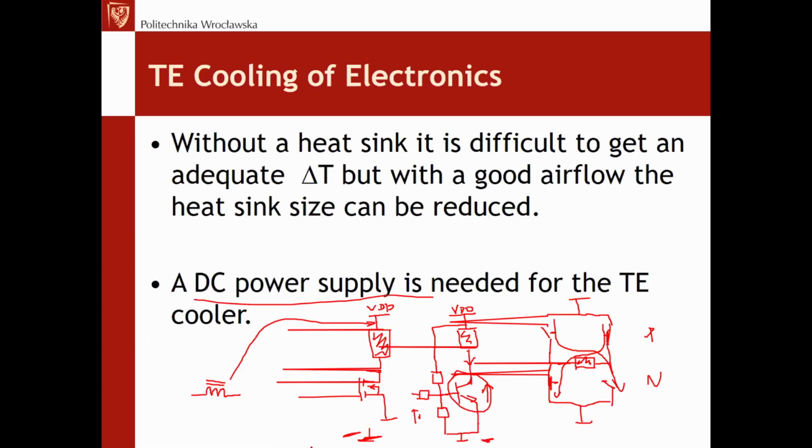This inductance reduces the efficiency problems of this Peltier element during switching, because the Peltier element doesn't like steep switching, which would be the case in this configuration. To avoid problems, since a lot of current is required, there has to be a strong coil, 10 microhenries or 22 microhenries is good enough for 1 or 2 amps.